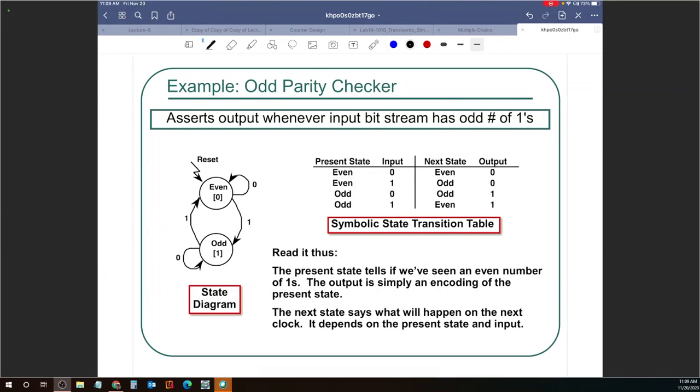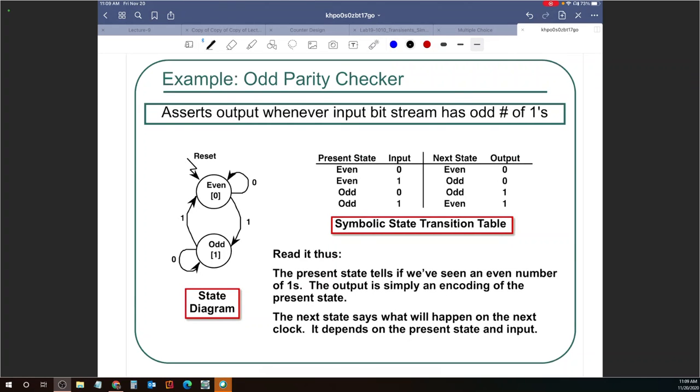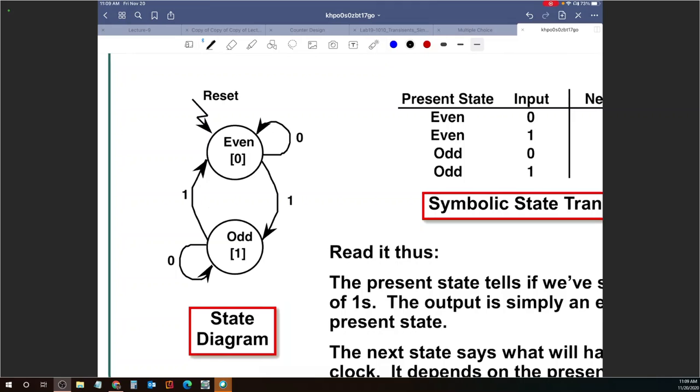All right. So I'm going to assume that you guys were clear on that. Now let us talk about the state diagram. Whenever we are designing a finite state machine, the first step that we do is to draw the state diagram, just as we did for our counter design. And our state diagram has circles and arrows or arcs. Our circles indicate the states.